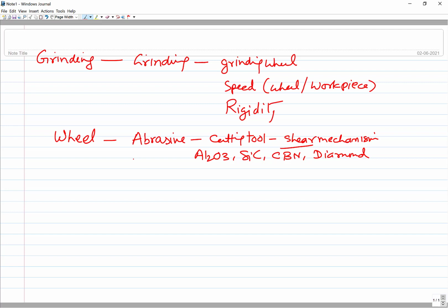If the two are having affinity of any sort, then it is not good. The compatibility between the abrasive and workpiece must be good, and they must be inert. If there is any kind of incompatibility or affinity in terms of reactions with each other, then it will be degrading the abrasive and degrading the life, degrading the cutting ability of the abrasives very fast.